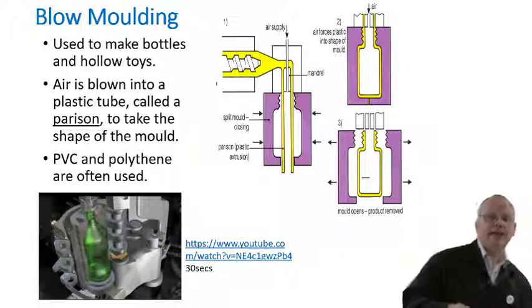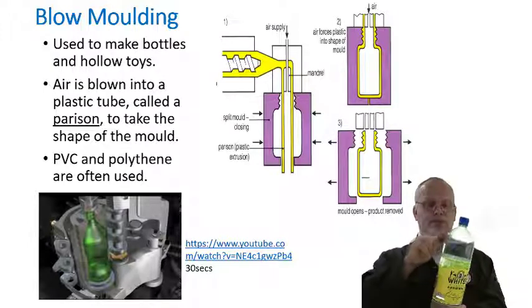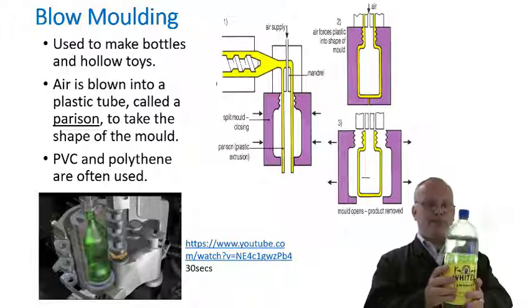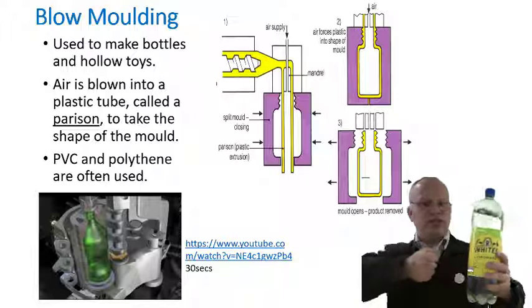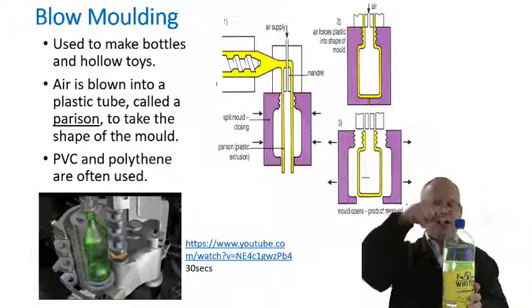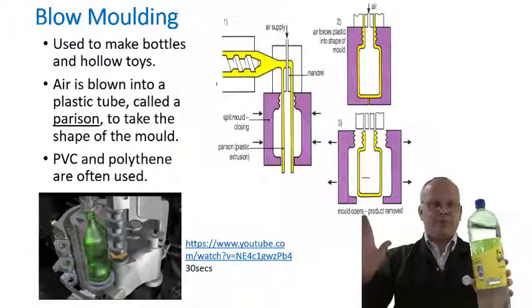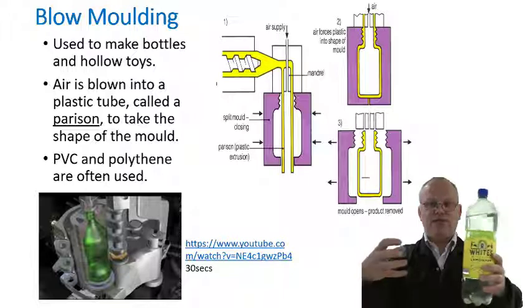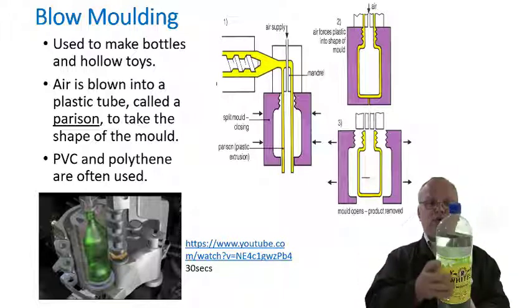Another good example to look at is this drinks bottle here. This uses a material called polyethylene terephthalate, PET, and PET has a really good tensile strength. It can take loads of pulling. Now this isn't pulling in some respects. A carbonated drinks bottle is exerting loads of outward pressure. So what that material has to do is it has to be able to withstand that pressure by pulling back. That's why tensile strength is important.